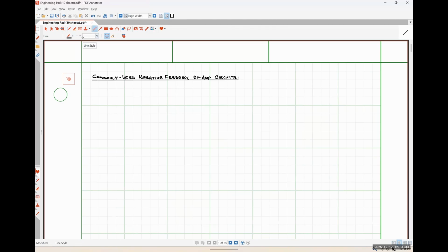Okay. So all of these are going to be negative feedback circuits. And as I mentioned at the end of our class on Monday, whenever we have a negative feedback circuit, we can just use the ideal op-amp rule because the amount of error that's introduced is going to be so small. So these circuits will behave in this way, even if we did our full-on analysis using the practical op-amp model, or if we just used the ideal op-amp model.